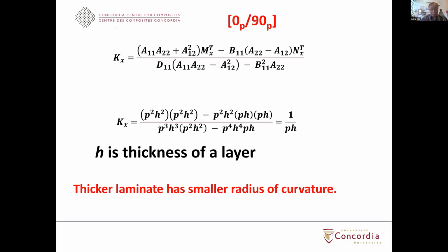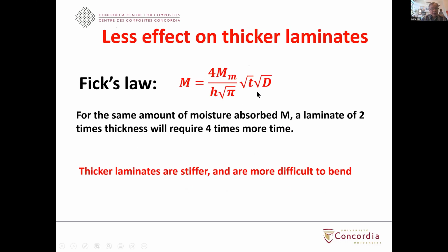And then also the effect of thickness due to the moisture and also the temperature. If you take a look into Fick's law, it shows that the amount of moisture absorption is proportional to the maximum amount. And the important thing here is the time. T is the time and H is the thickness. You can see that the amount of absorption is inversely proportional to thickness and proportional to the square root